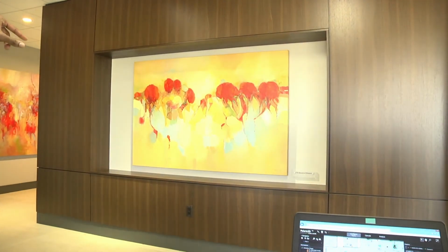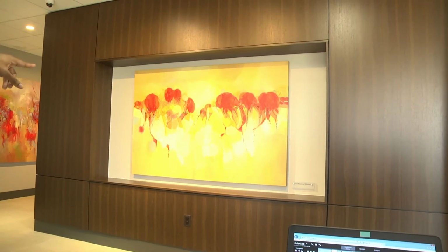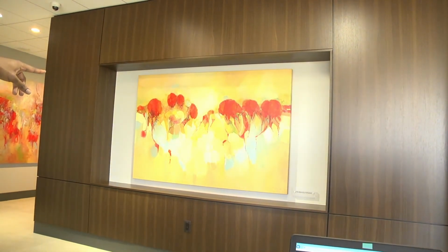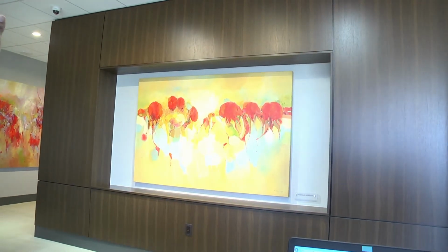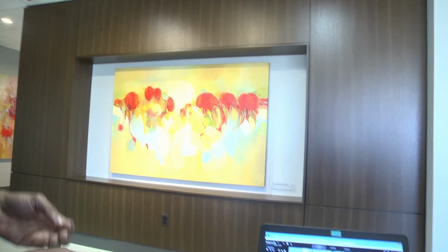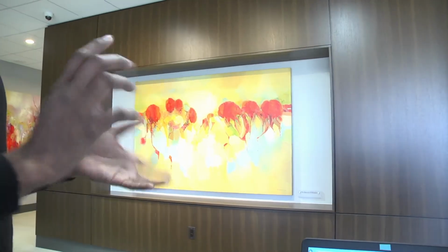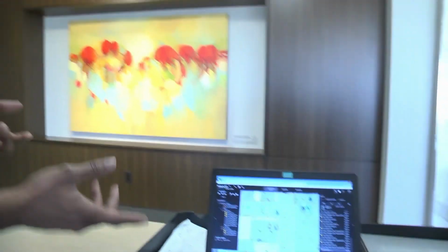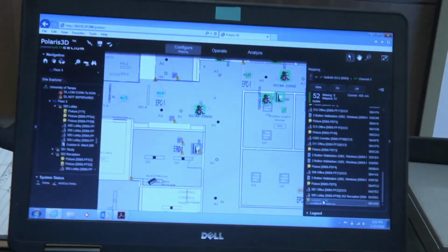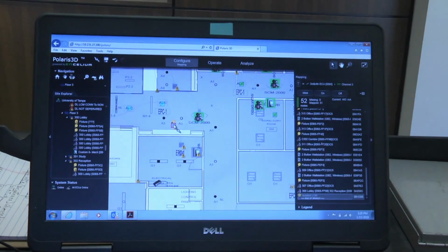Once you hit the wink button and you look at the space, you see the lights flashing off, on, and it's going to dim, and it's going to come back up, right? So the winking process is a process of triggering the device so you can visually see what it is. You've identified it, so you've got to go back to that device, click and hold, and drag it over to your floor template on the floor plan. Link is formed, let it go.